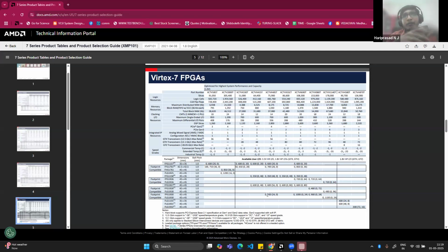One of the tests we used to do is a temperature test. There are temperature chambers available, like the in-space laboratory, and in Bangalore there is a laboratory called Tarang from Wipro, and Tata Advanced Systems, where they do this kind of test. We can take this FPGA board inside that chamber, where we can bring the temperature to -40 degrees. We will be powering off the device. If your device is powered on, it will be generating some heat, right? FPGA itself generates heat. Because of that heat, even if you take -40 degrees, the surface temperature of the device will be maybe 20 or 30 degrees.